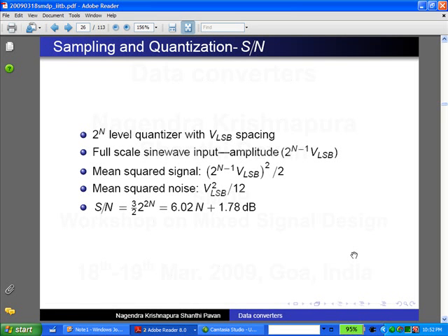By the signal to noise ratio, right? When you have some signal and noise, you describe it by the signal to noise ratio. And if the signal to noise ratio is above something, you can identify the signal, otherwise you can't identify. That's how you usually do it. For instance, if some noise is added to this, if the noise level is above some value, you won't be able to find out what I'm speaking. Similarly, this quantization error is described as noise, and here I'll calculate the signal to quantization noise ratio or quantization error ratio.